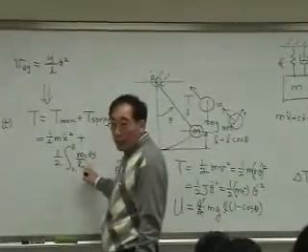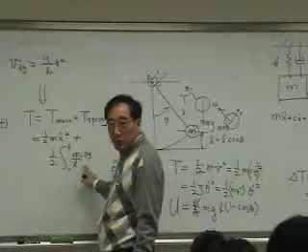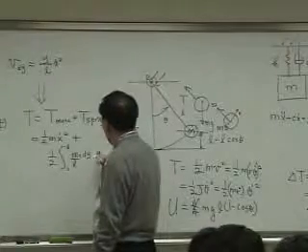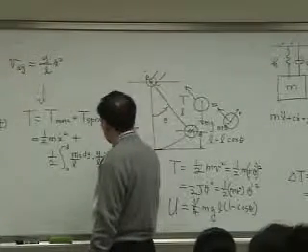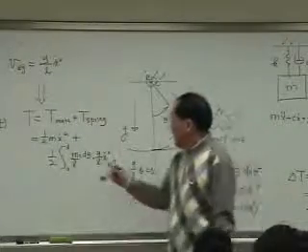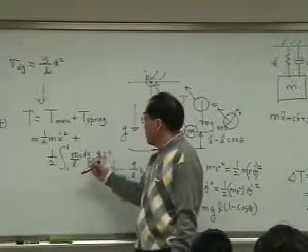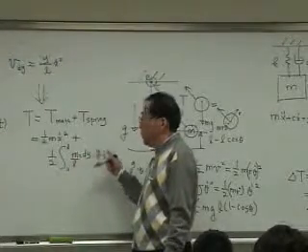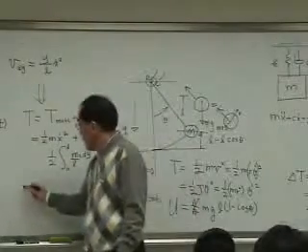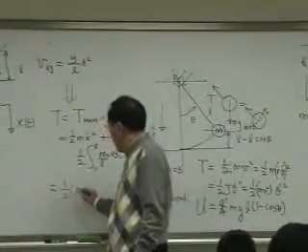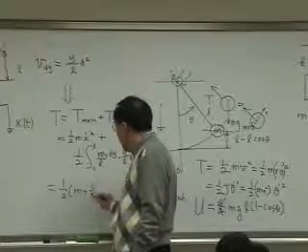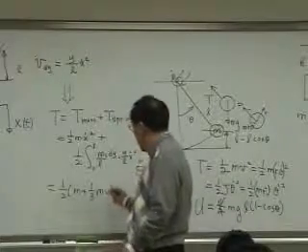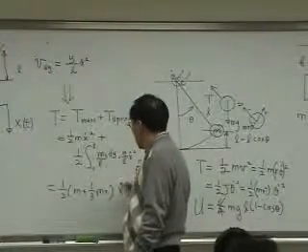Okay, and then I have a length dy, so therefore this is the mass. And the velocity is y over L x dot squared. And then I want to integrate with respect to y from 0 to L, so this one and this one can come out, and this ends up with 1/2 (m plus 1/3 ms) x dot squared.